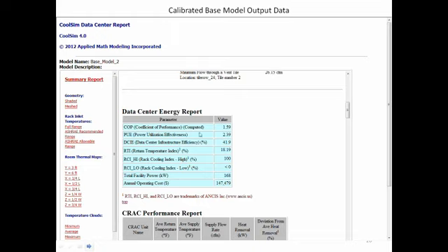So the summary report contains this, and there's a few things we can note about this right away. COP, Liz, 1.59. Pretty low, pretty low. Awful. Yes. PUE 2.3, which means that we're spending as much electricity powering the cooling systems as we are powering the IT equipment, and then some. That's right. RTI, 18%, just awful.